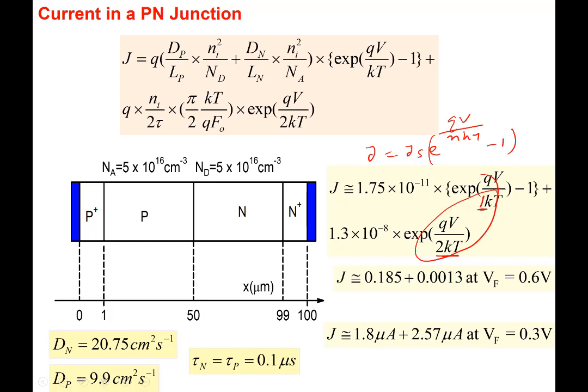All right, so this is an important current that we forget when we are at higher bias, but it is important. Imagine that you take a solar cell and use it under low light intensity. Under low light intensity, this is what would dominate. So at various places you find you need this ideality factor 2, and at various places this becomes important.